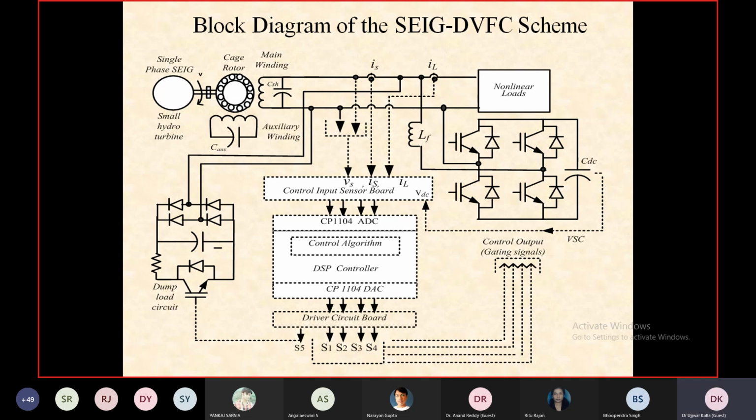So for a sinusoidal voltage source, non-sinusoidality may be considered as a non-linearity. And total harmonic distortion is a measure of non-sinusoidality in the waveform.